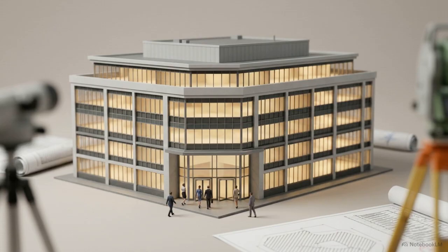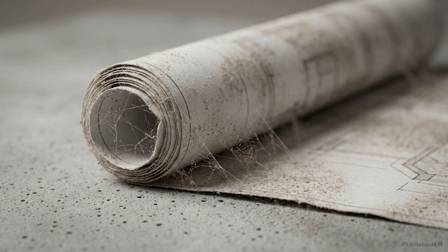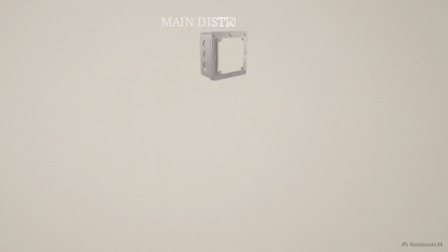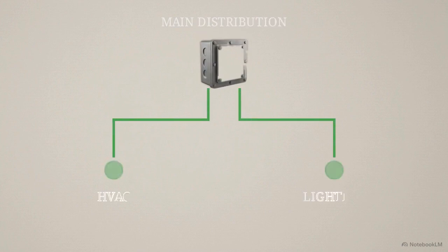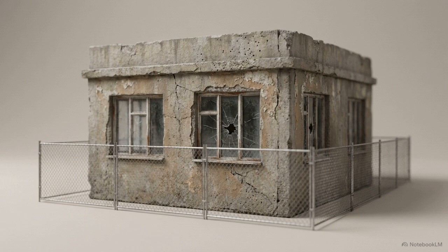When the building is completed, the documentation matrix shifts again. Drawings evolve from instructional manuals into diagnostic tools. Facility managers rely on as-built drawings. During construction, field modifications are always made to solve on-site realities, meaning the original GFC drawings cannot be used for post-construction maintenance. For hidden utilities, MEP-concealed layouts, specifically electrical single-line diagrams, allow electricians to trace and isolate power zones without breaking through finished walls. Eventually, the structure reaches the end of its life.